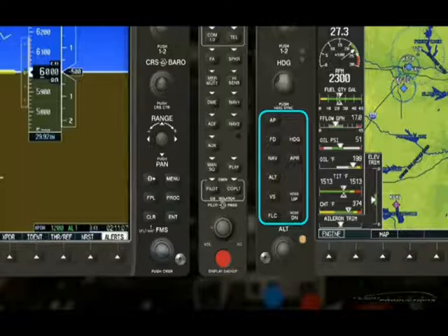the Vertical Speed key. When activated, the vertical speed mode and the vertical speed bug are displayed. The Flight Level Change key, used to fly to a selected altitude, and the Nose Up and Nose Down keys, which are used to control pitch reference in the pitch hold, vertical speed, and flight level change modes.